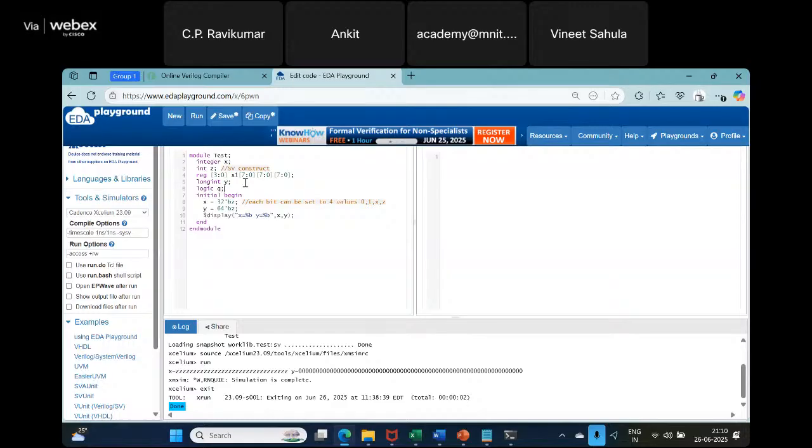And it can be used in the place of either reg or wire. So this is a very useful thing. See, earlier when I was trying to do many of these exercises, sometimes I used to forget that it is a reg, right? So I used to go back and add reg. If you had declared those as logic, none of this is required.